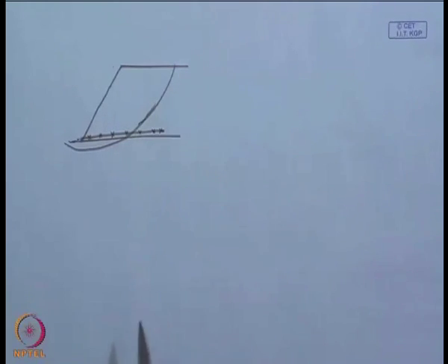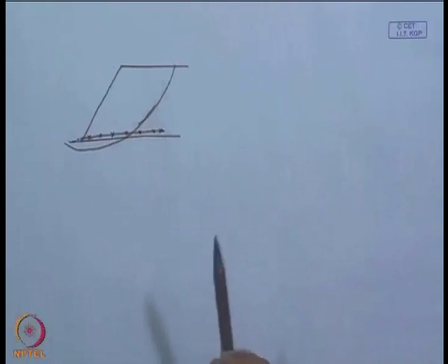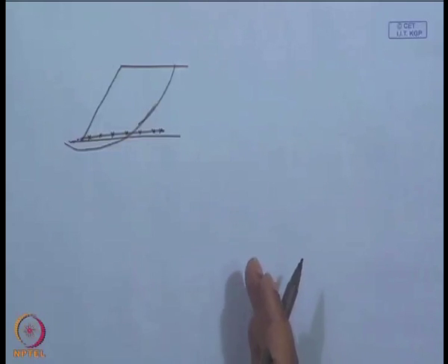So, that means these are the techniques that we can use to make the design safe for the seismic condition. One example that I have already explained is how to shape this design for a retaining wall, so that we can account for the seismic condition also. Then we can also make our slope stable if I provide reinforcement in the seismic condition. So, that is one option of making the structure stable against seismic condition.